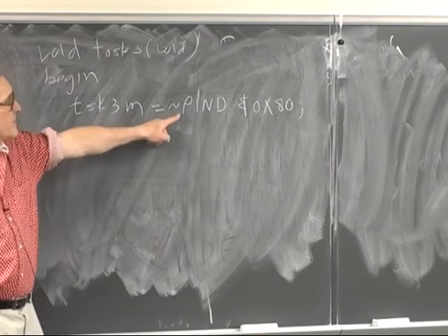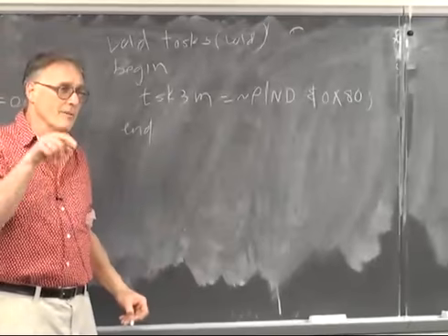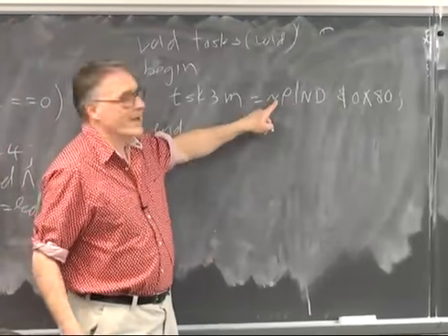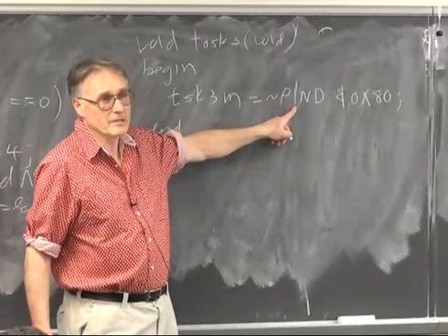And because the push buttons on the STK500 are inverted logic, when you push them they become a 0, it's easier for me to think about it if I just automatically invert them before I do anything with them, so that it becomes positive logic.